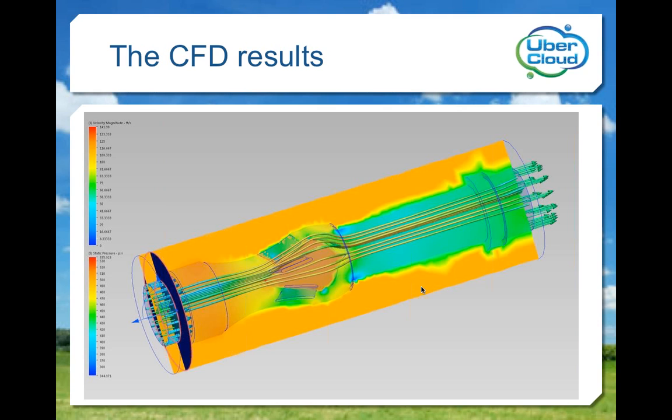The cross-section plane shows the distribution of the pressure at the fluid boundary and about 450 psig at the discharge. Considering that my prediction of the C sub V for the valve was 70, and this simulation predicted 70.71, these were very reasonable results.